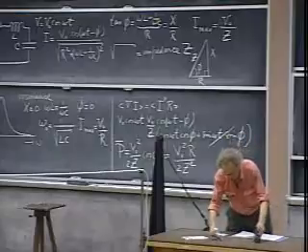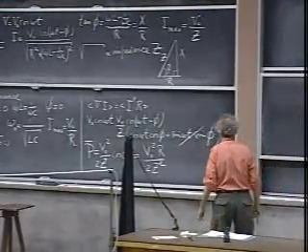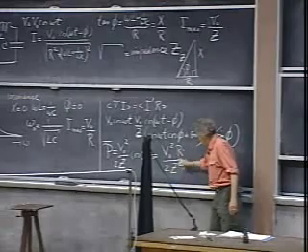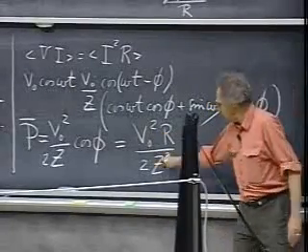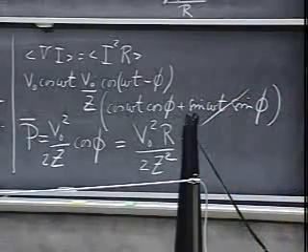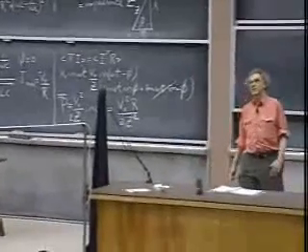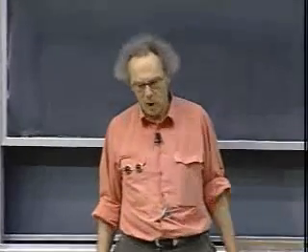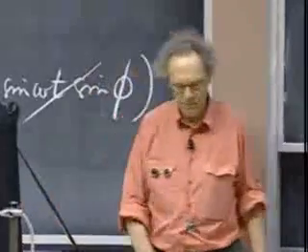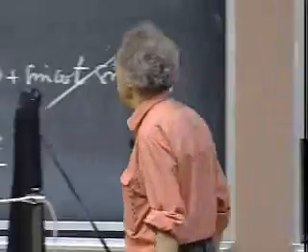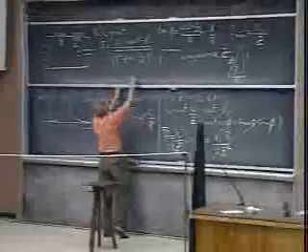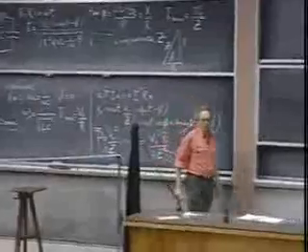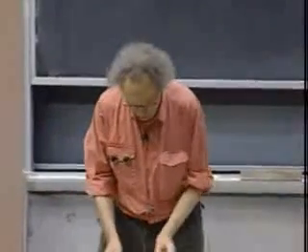So now we can look at resonance. It's always a very special situation. When we are at resonance, Z equals R. So you replace this capital Z by R, and then you find V0 squared divided by 2R. That's utterly trivial. You could have predicted that. It's really Ohm's law staring you in the face. There is no self-inductance, and there is no capacitor at resonance, so you might as well have treated it as a simple system only with R, and you find immediately that answer. At any other frequency than omega 0, Z would always be larger than R. You see that immediately here, and so that means that the average power would always be lower. So it's only at resonance that you generate the highest power possible.